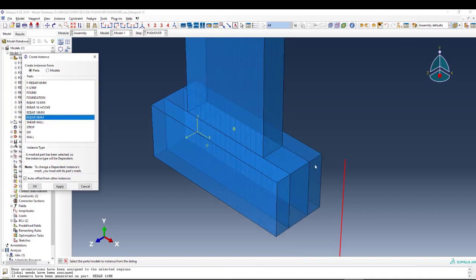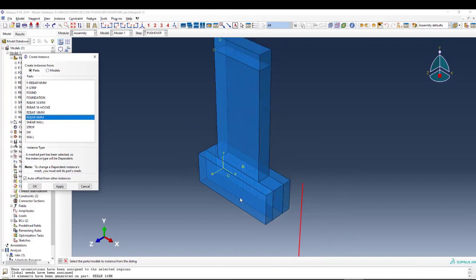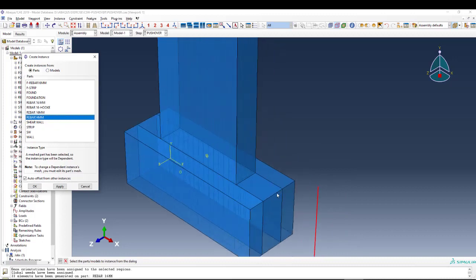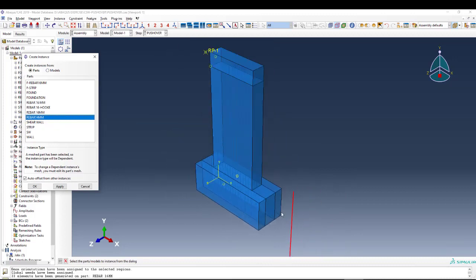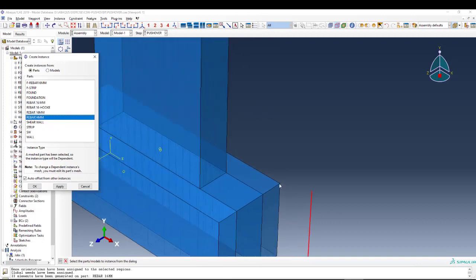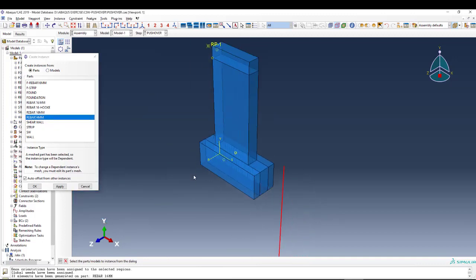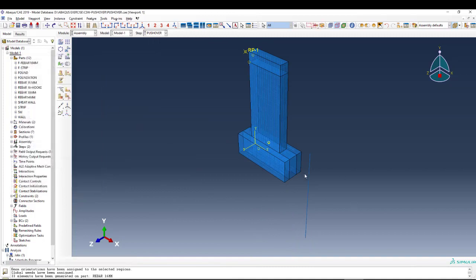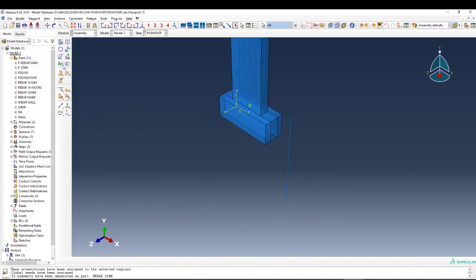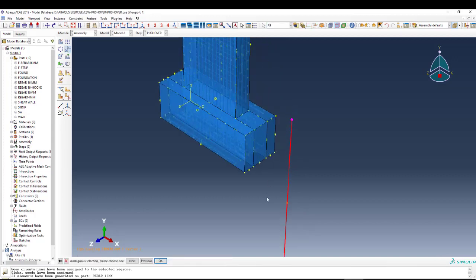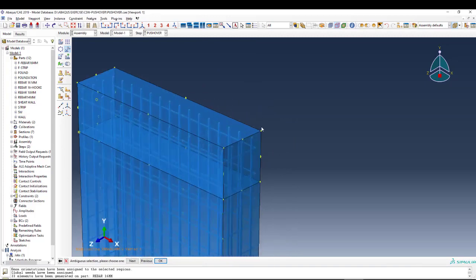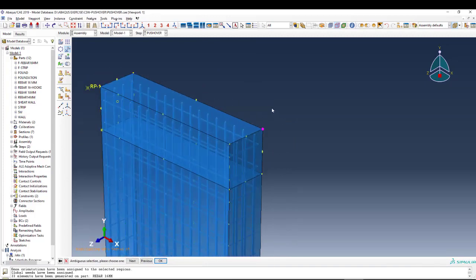So we have like 30 millimeters cover on this side, 50 millimeters on this side, 40 at the bottom, 30 on this side, 30 millimeters on this side. So you will shift. You can take a point, or you can bring this point, and then let me show you one. This is one of the elements. I will move this directly to the inner top of the structure here.